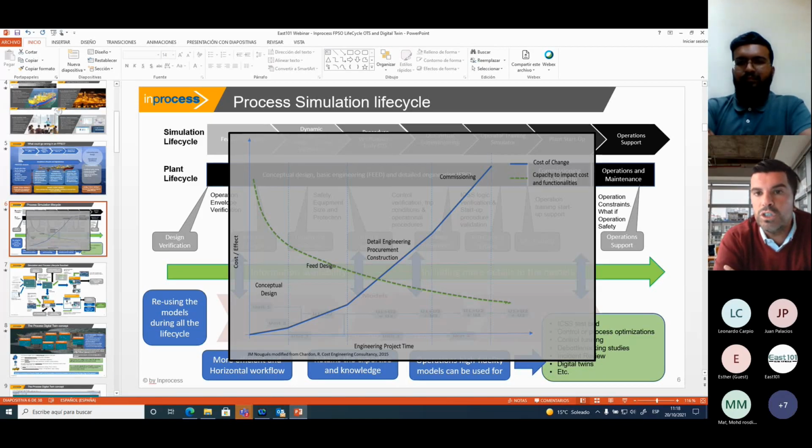But the other thing is the computational time, of course, when you are talking about a training tool and you are in front of an OTS, because it's the kind of feeling that the operator has of their plant. So at minimum, of course, we need to guarantee that it can be run at real-time factor. This is the minimum. But of course, in all the OTSs, we are asked not only to match the real-time factor, but to be able to run faster than the real-time factor.